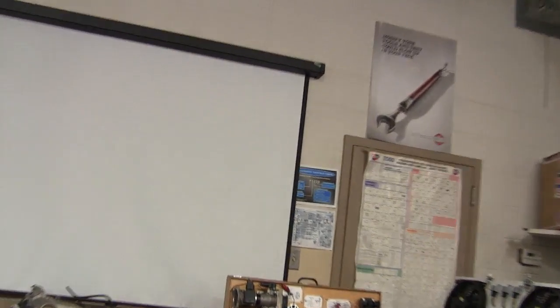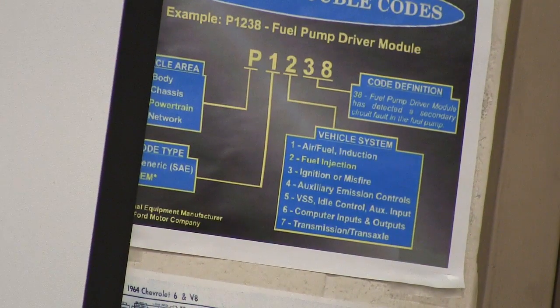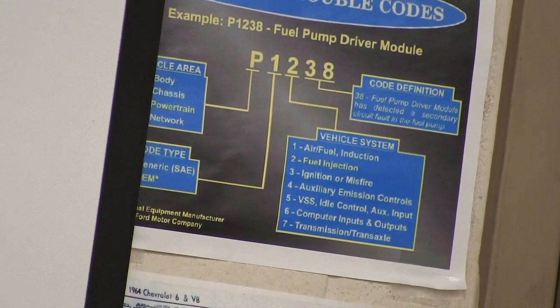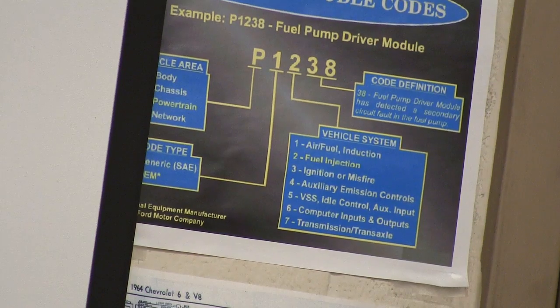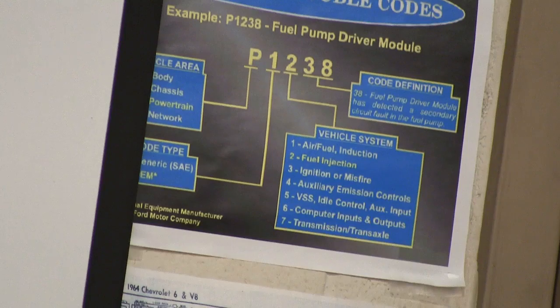I can't see it from here, unfortunately. I think it says airflow something. All right. This is where we're looking. Air fuel. There you go. See, nothing complicated about that. Yeah, I figured that out, but I meant what exactly is a P0102? Yeah, it basically means, as I remember, you've got a low, there's no mass airflow signal.